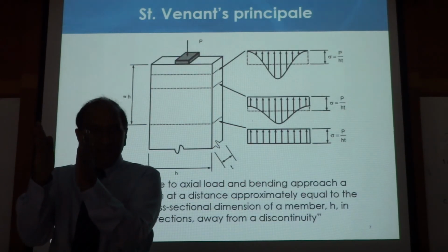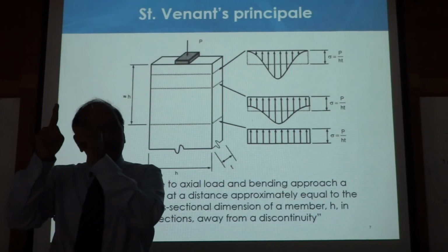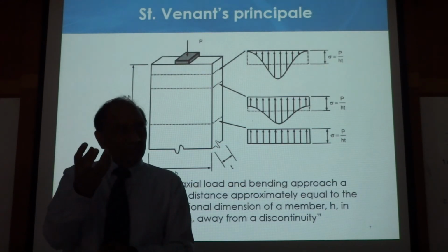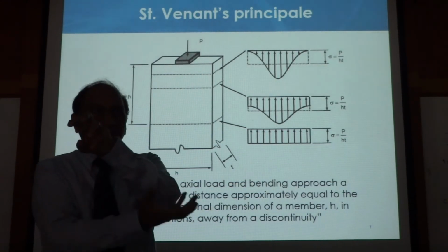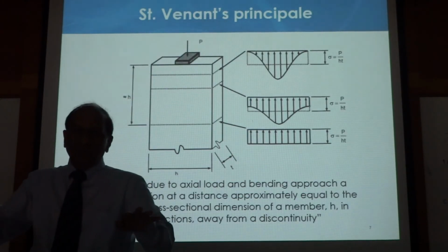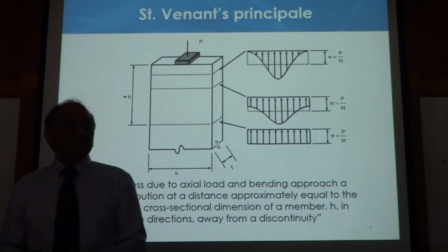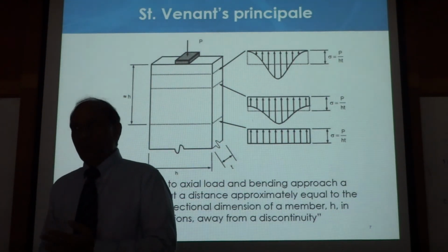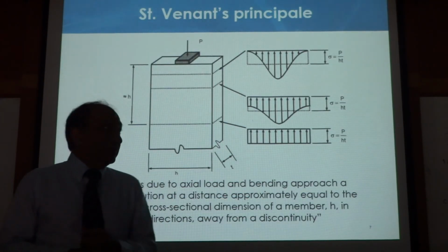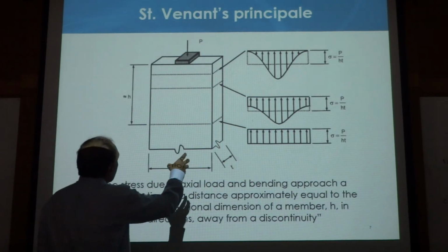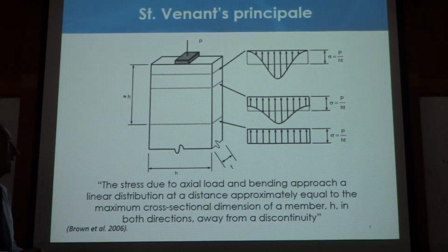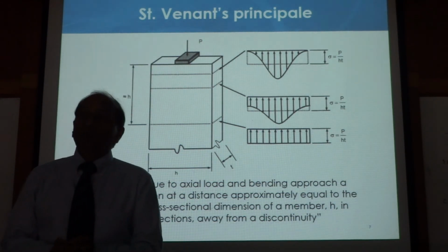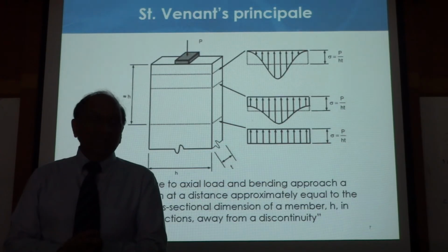You don't design for infinite deformation, because bodies do not deform infinitely, they distribute. With a local disturbance, after some time the particles take the force and the effect becomes smaller and smaller, and then it is as if everybody is sharing the load in the same way. Correct? This also comes from Saint-Venant's principle, and it is quite important and interesting for us when we go into the details of the Strut and tie model.